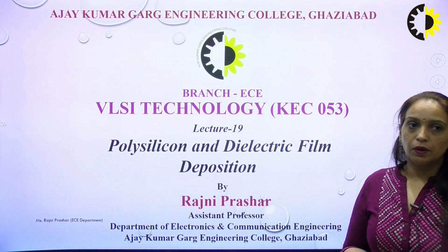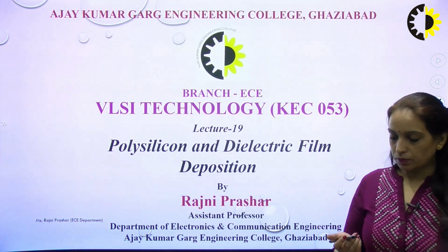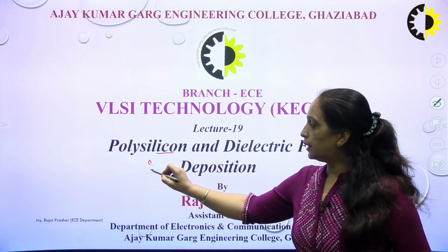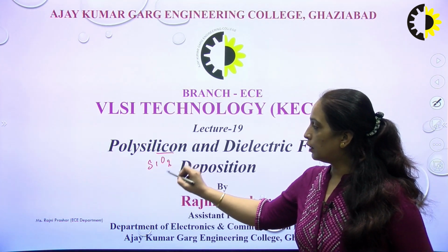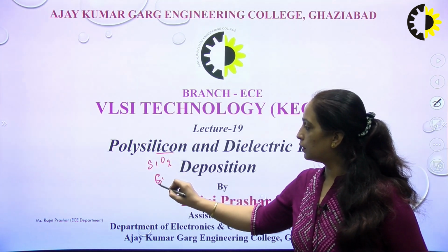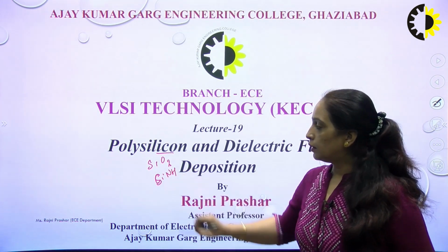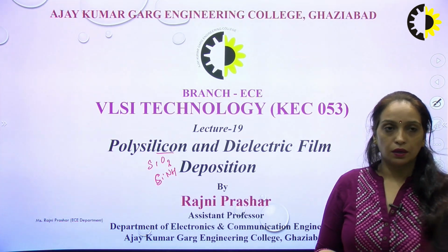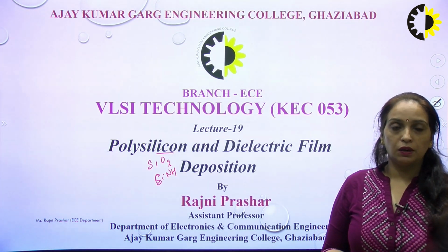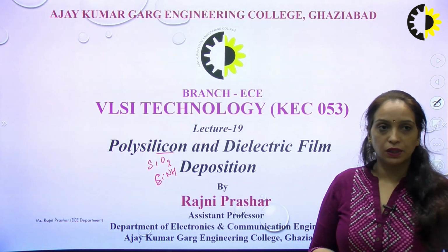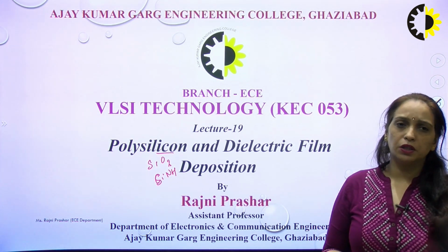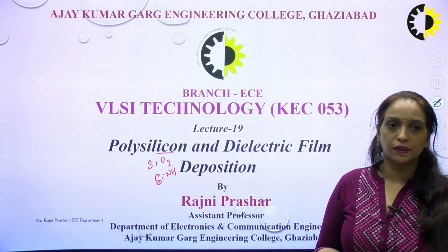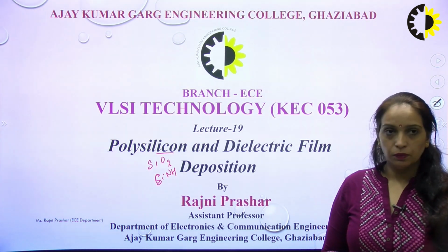In this lecture we are going to study the various materials like polysilicon, silicon dioxide, and silicon nitride. For all these materials we are going to study what reactions are used for their formation, what the temperature range and pressure range are, and what process reactors can be used for the deposition process.